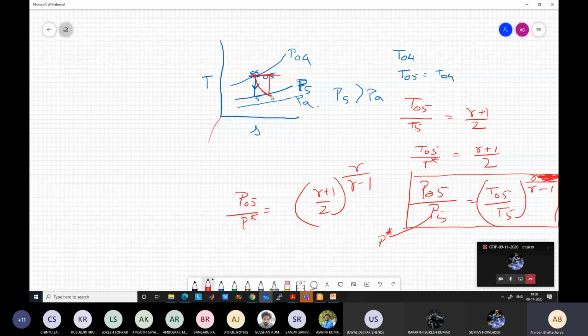Everybody gets confused. So let me just make you understand this part. Okay, this diagram is not accurate. Let me draw it in an exaggerated way. So the temperature at point 5 is equal to that at point 4. Okay, it is the same temperature, but it is at a different location because entropy has increased. The actual point 5, let us call the other one 5s, because that was the isentropic case.